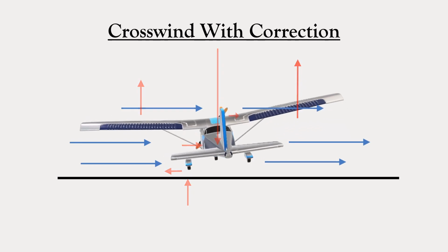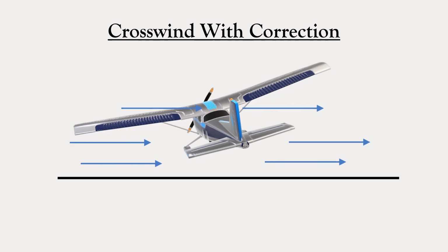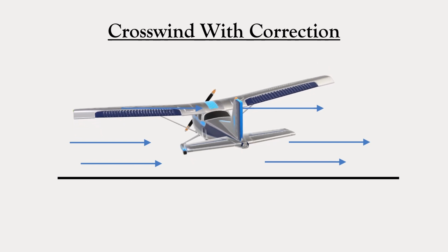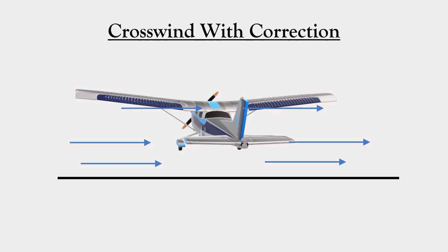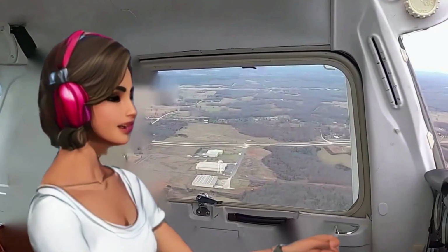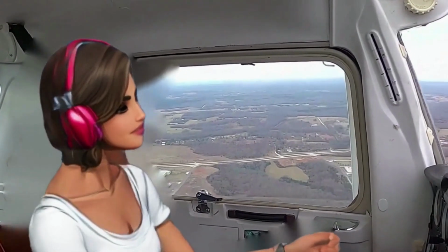As the airplane lifts off the runway, it begins to bank to the left and to yaw to the left. Once the airplane has turned enough to establish a crab angle, then you'll level the wings and you fly away, tracking the runway centerline. So, do I need to do that on every takeoff? Even if there is only a little bit of crosswind?